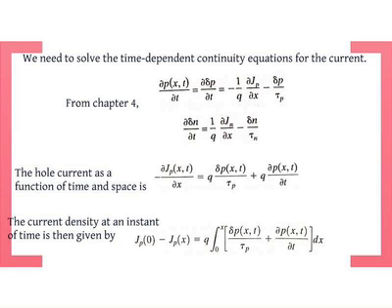So you can model it. We saw this before from chapter 4. The rate of change of concentration of holes. Remember the hole concentration is a function of position, because there's that diffusion happening, and a function of time. The rate of change of concentration as a function of time is basically that. Just to remember our notation, P as a function of x and t equals P naught, which is a constant, plus delta P.